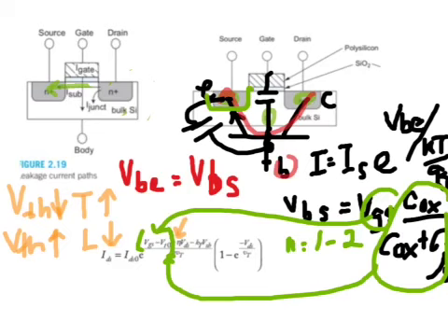And there is an effect called drain-induced barrier lowering, where high voltages, high E fields in the drain here induce a reduction in VTH as well. And so the effect of DIBL, drain-induced barrier lowering, is captured by this eta parameter here.